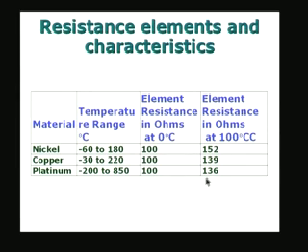The main difference between resistance thermometers and thermistors, which we will see later, is that this variation of resistance is very small in the case of resistance thermometers, and the resistance increases with temperature. In the case of thermistors, it is going to decrease with respect to temperature and also decrease by a larger fraction. And therefore, thermistors are more sensitive, but they have a smaller range compared to the resistance thermometers. The case being, we are talking mostly about the platinum resistance thermometer.